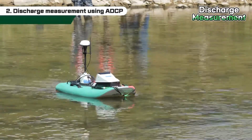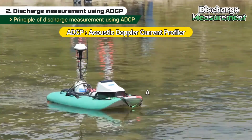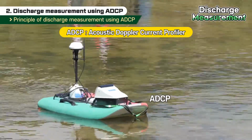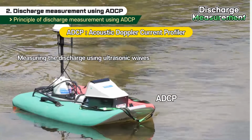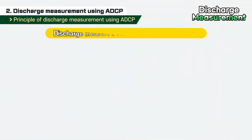Now let's take a look at the second type of measurement device, ADCP. ADCP stands for Acoustic Doppler Current Profiler and is an ultrasonic current meter that measures discharge using ultrasonic waves. Discharge measurement using ADCP basically utilizes the Doppler effect.